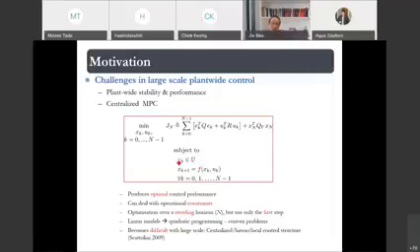So all the control actions have to belong to the feasible control action set, which is described as U here. Now, as I mentioned just now, one way to control the plant-wide process is to use a centralized MPC. So in that case, the model we have here describes the behavior of the entire plant-wide system. So it'll be a very complex model.